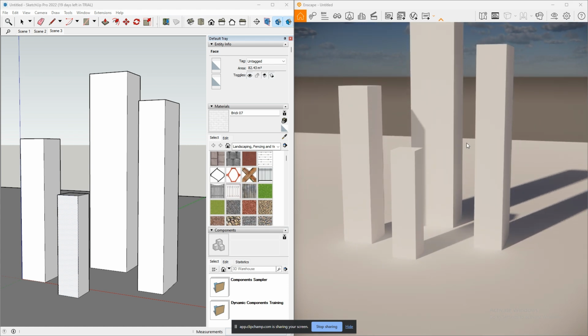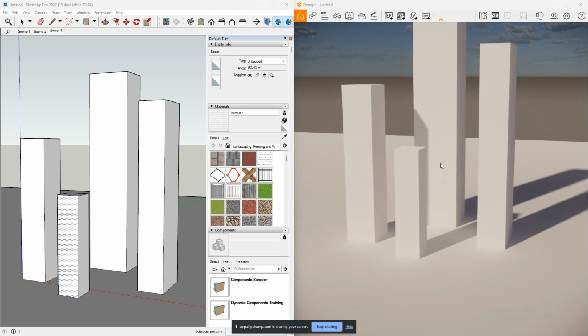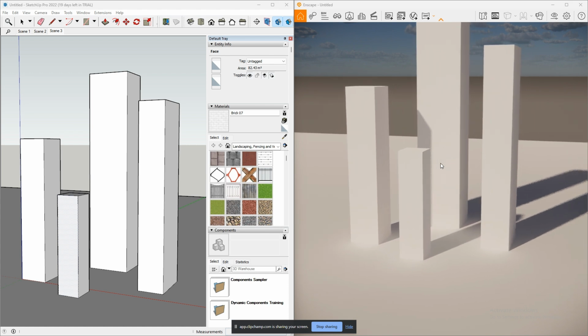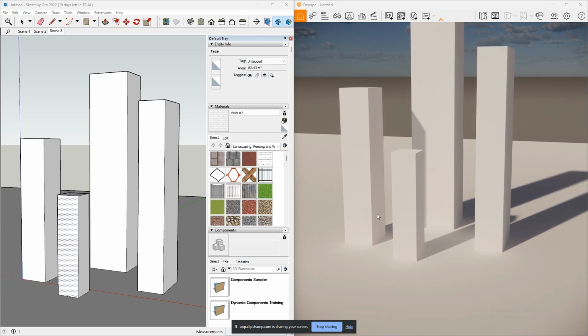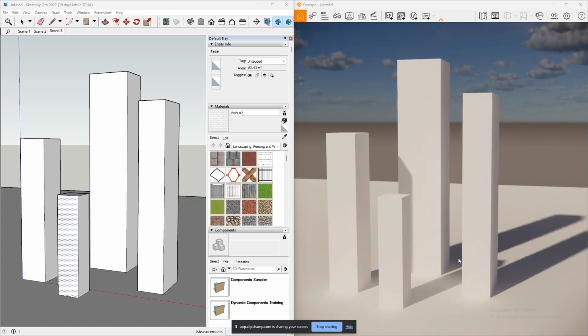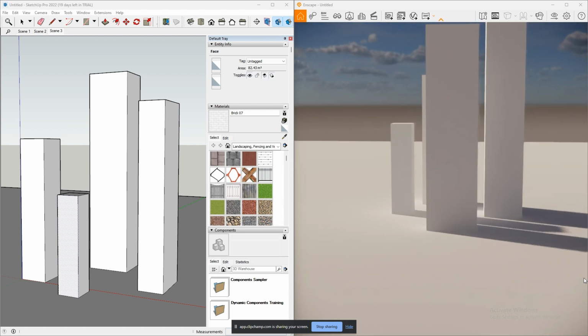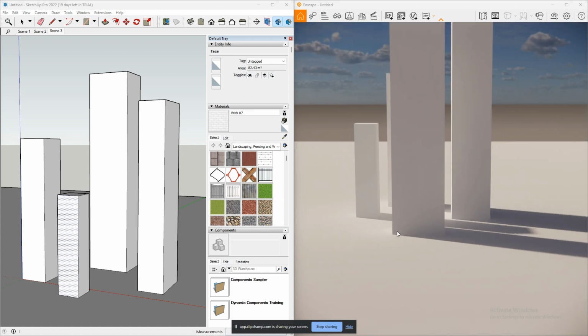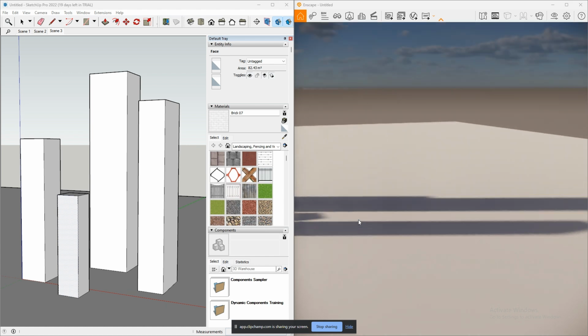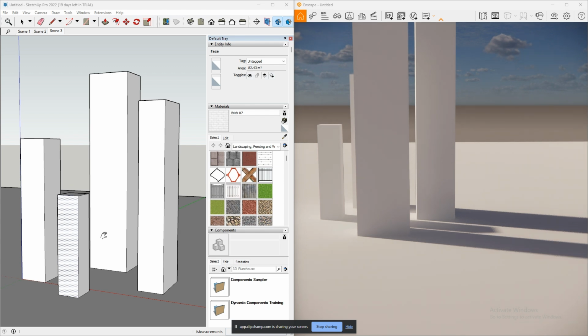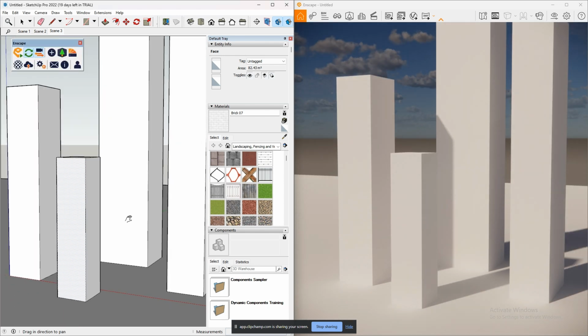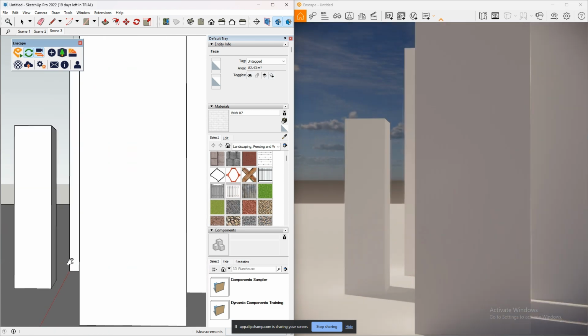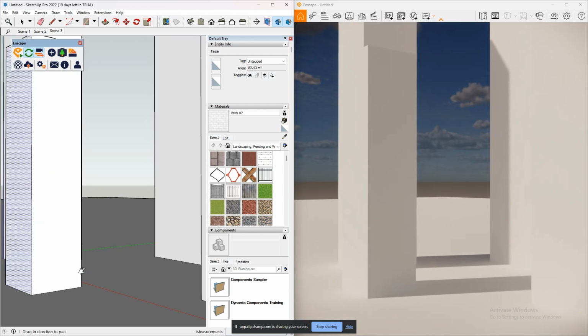You can also mimic the WASD movement controls with the scroll wheel button, such as this, moving your mouse around your mouse pad. But as I stated, the movements in Enscape are not the best, mainly used for moving your camera around. Scroll wheel will also, as you could expect, allow you to move forward and backwards. However, I mainly prefer to just use the SketchUp movements, as I find them a lot more fluid, a lot more quick and snappy.